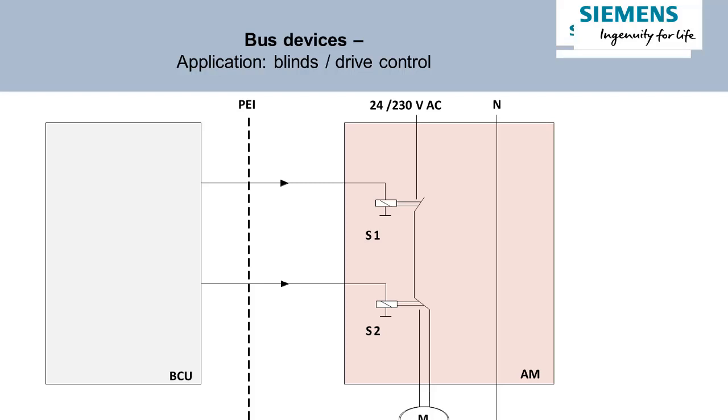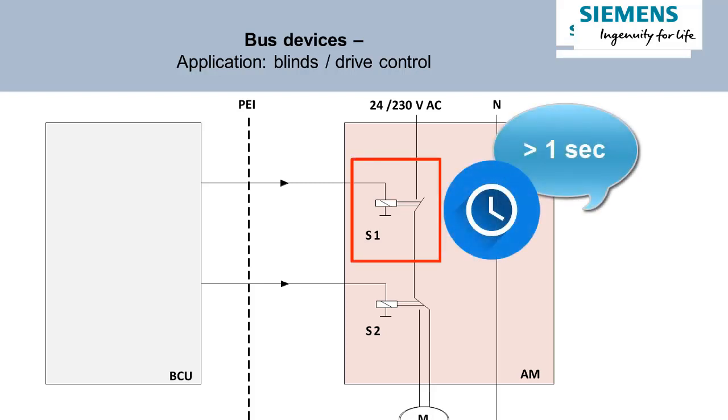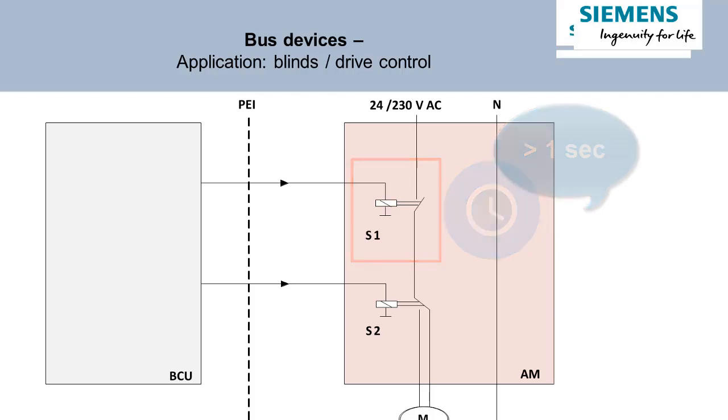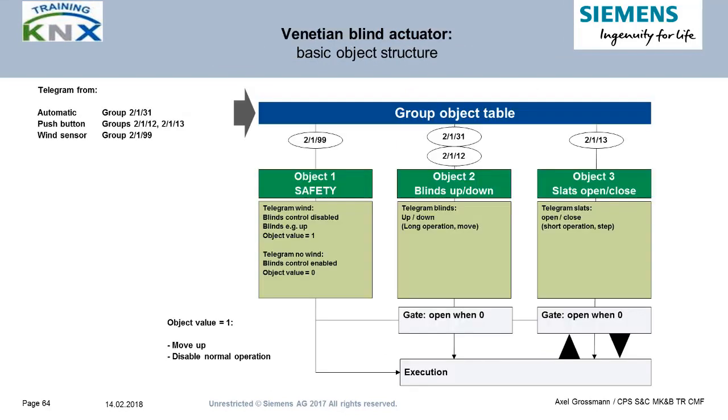When you reverse the spinning sense too quickly, the impact of this arc is boosted and the contacts wear off too fast. Therefore, the relay S1 is also subject to a reverse pause timer, normally 1 second or higher. This reliably avoids excessive contact burn-off.